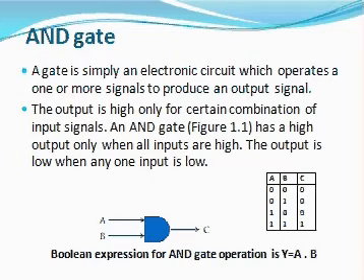Next we are going to see about the logic gates. A gate is a logic circuit with one output and one or more inputs. The output signal occurs only for certain input combinations. The input and output signals are digital in nature, that is 0 or 1, or low or high. All the possible input combinations and their corresponding output conditions are noted in a table known as a truth table. In a digital system, two different voltage levels are used to represent the logic levels 0 and 1. A high voltage represents logic 1, and a low voltage level represents logic 0.